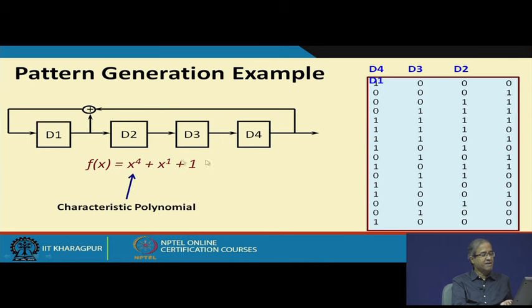You see, for LFSR the all 0 pattern has a very, you can say, dangerous implication. Once you load this LFSR with all 0 pattern, it will remain in the all 0 state, because XOR of 0 and 0 will be 0, 0 will be shifted. So, right shift and 0 comes in, so it will remain all 0. So, whenever we want to use LFSR for a data generation application, we should never load it with all 0, and this is a very good kind of LFSR we have chosen, because we are able to generate all the other 15 patterns excepting 0.